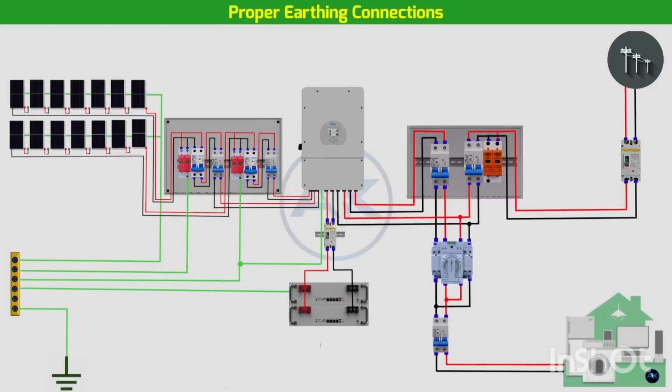5. Tying it all to earth. Finally, all these grounding wires, from the solar panels, the inverter, and the AC panels, must be tied together and connected to your main electrical service's earth electrode or ground rod. This is the final and most important connection, providing that safe path directly to the earth itself. Make sure this connection is solid, corrosion resistant, and low resistance. This is the heart of your grounding system. It's what makes all the other connections effective.